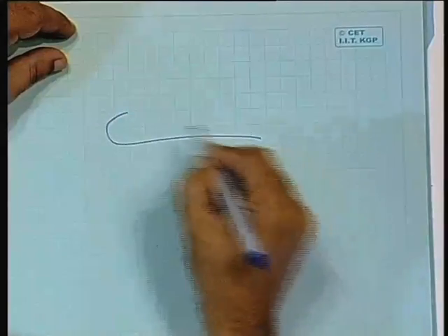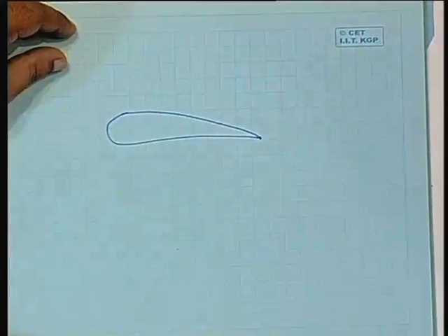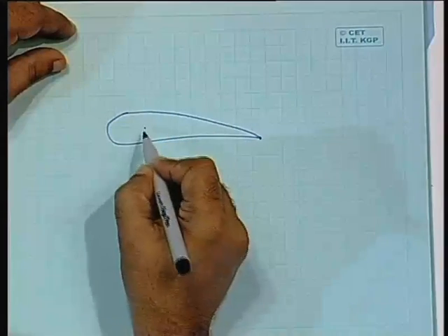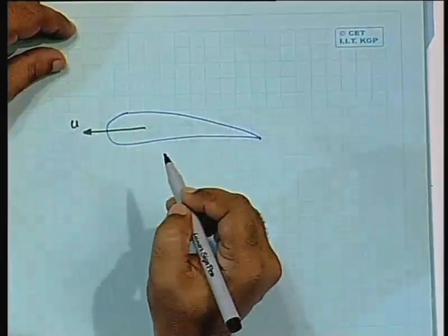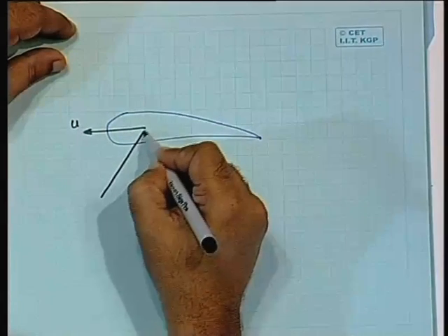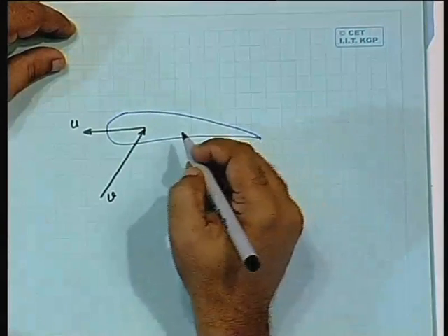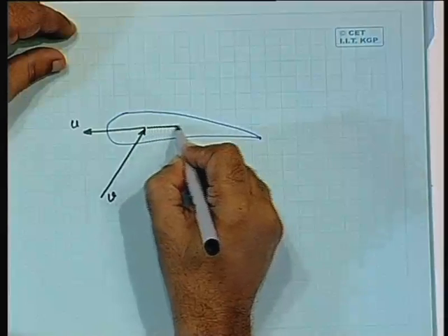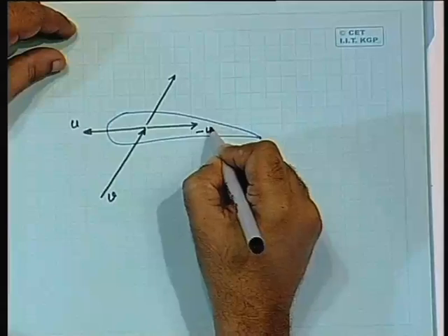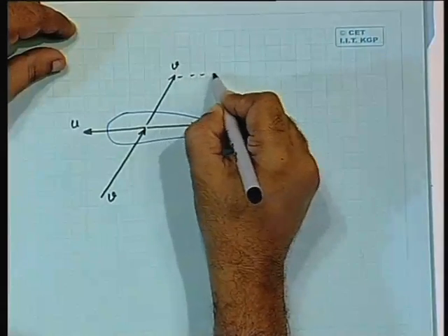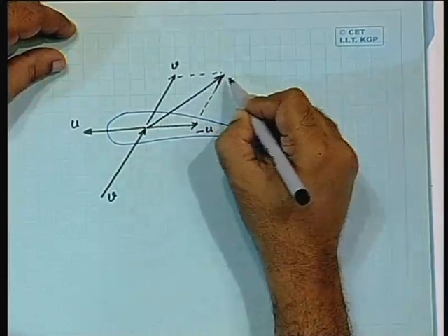You had the airfoil, and at some point we drew the direction of the motion u and the direction of the incoming airflow v, and so we obtained the parallelogram: minus u and v. Add them together, we have the vector for the relative wind w,